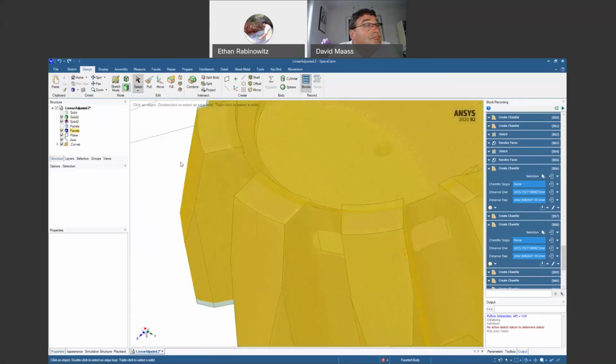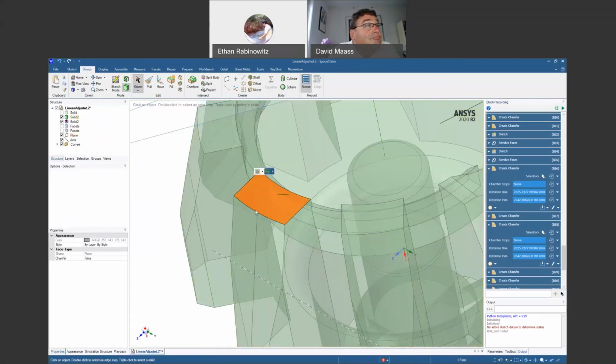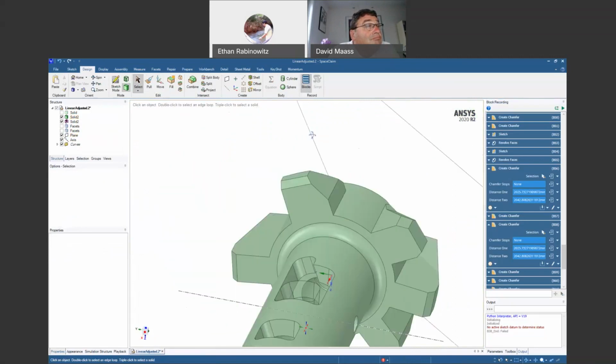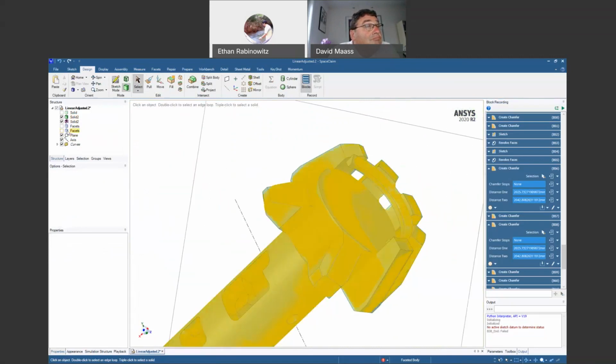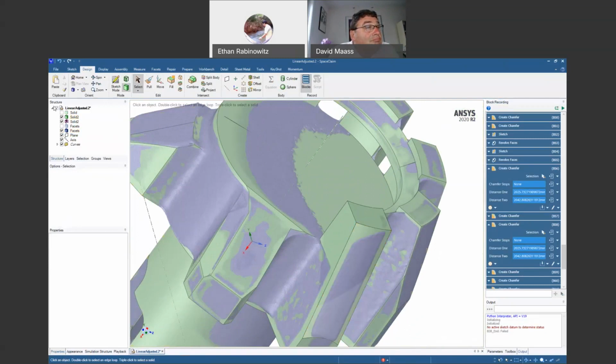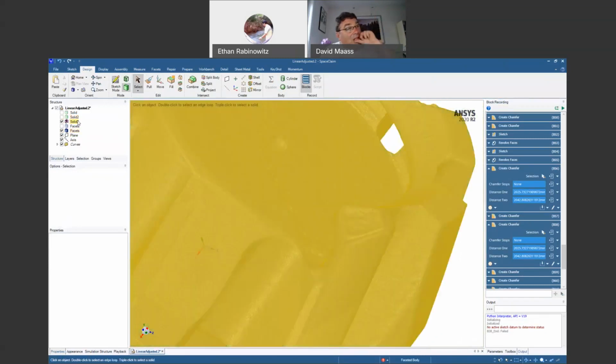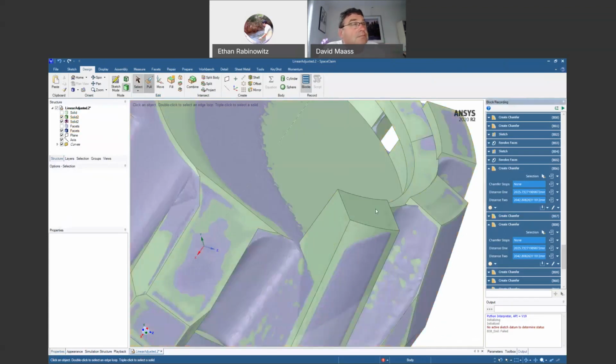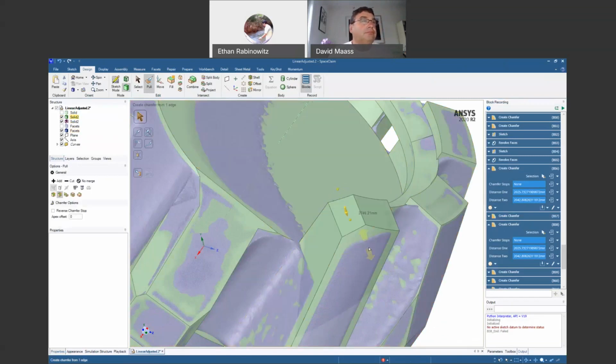Let's go ahead, let's hide the facets. Let's make this opaque. So here is the main shape of it. There are still a few individual cuts left to make. Like, this looks like it could just be a chamfer that we add. So like I could do something similar to the other side, come in, whoops, that's a round. So escape out of that, make a chamfer, adjust it in one direction. Then I could always even just grab the face of it and pull up, making an adjustment like that. Change this transparent again.